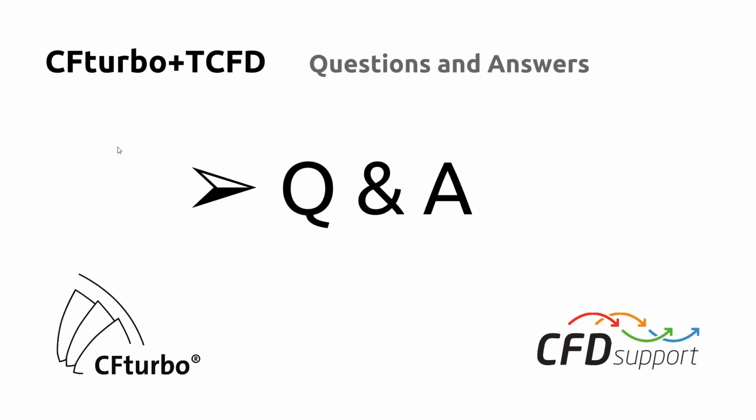Another one. Can CFturbo be used with a software like iSight for DOE and optimization? Yes, it can, because as I said, everything is parameterized, and also CFturbo can be run on a command line, which means you can put it into a batch process and use, for instance, an optimization package that controls all the changes in CFturbo, and then the proper exports will be done, and those exports again can be used in any simulation packages.